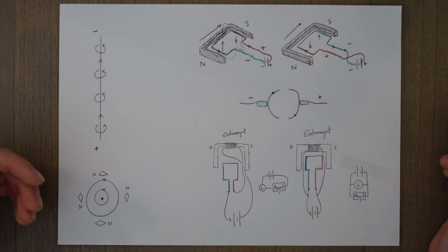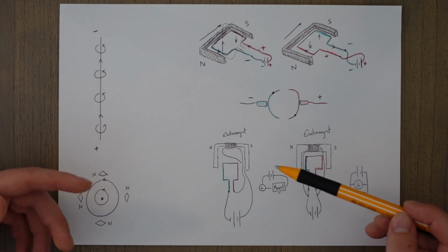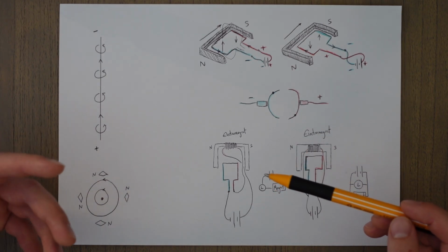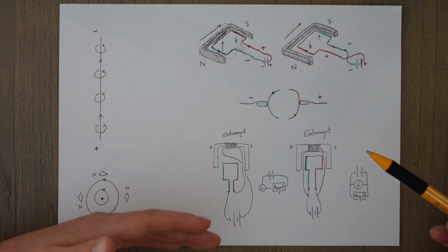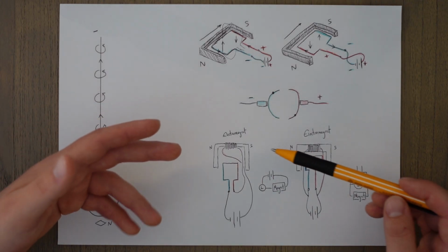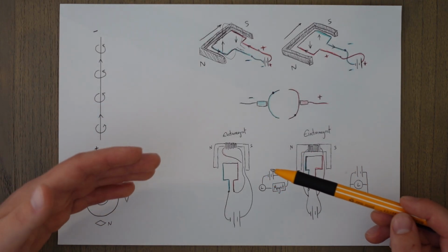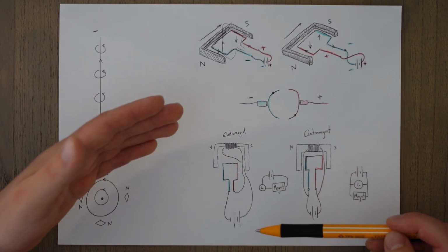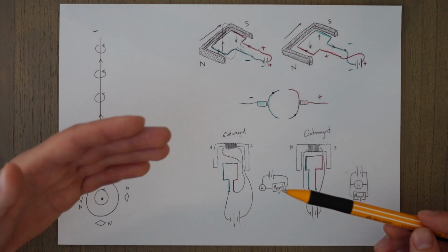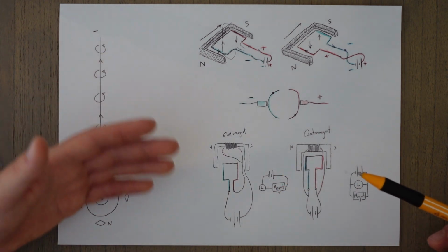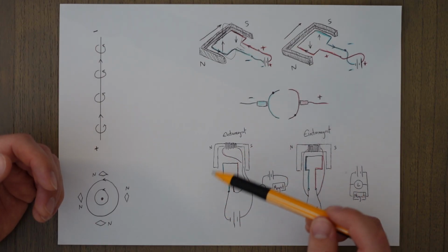We can also use electromagnets for the non-rotating stator element of the motor. This allows us to control the strength of the electromagnet by letting current flow or restricting it. If we use the same power source as we do for the loop, then the stator and the rotor can be in series, or the stator and the rotor can be in parallel. Let's look at series first, which is over here.